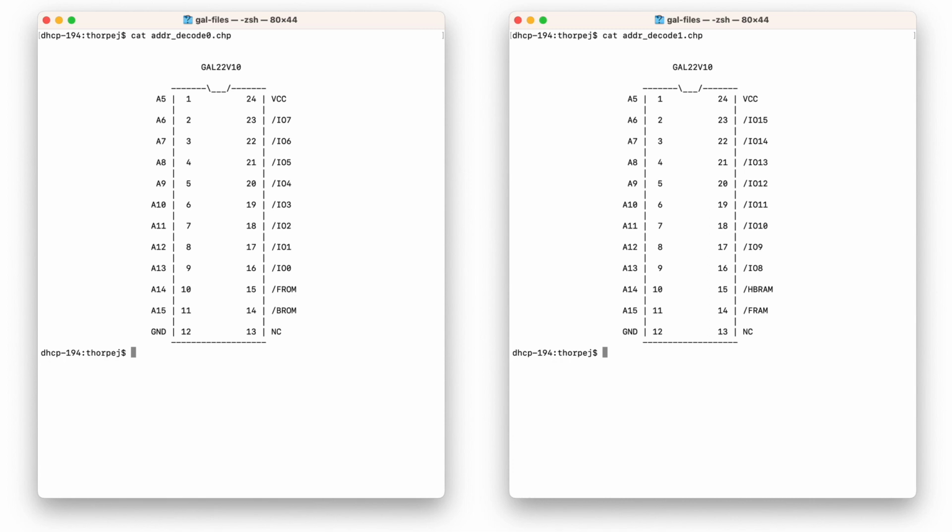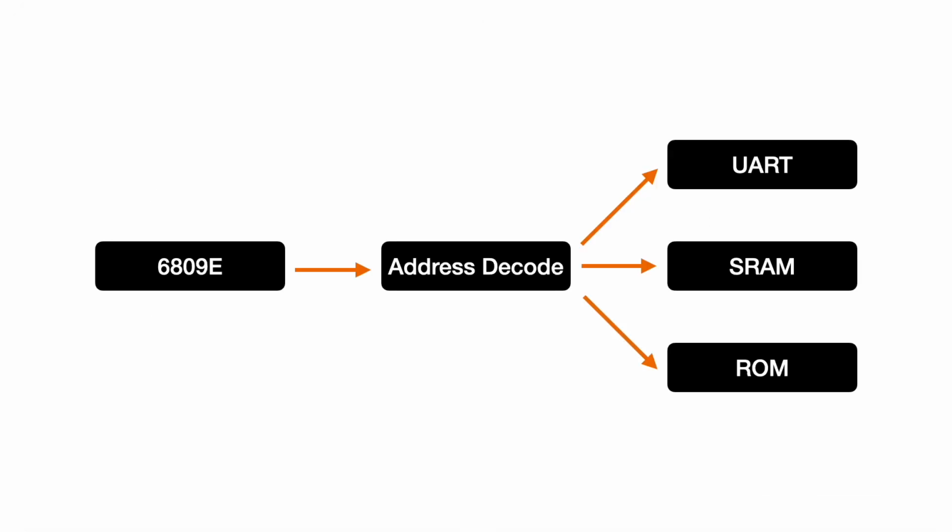So there you are with a complete address decoding solution and just 2 24-pin chips, with a low and uniform propagation delay no matter what address is being decoded. Okay, so we have another building block, but we're not quite done yet. We can decode addresses and select devices, but there's still the task of actually reading the data from or writing the data to the selected device. So let's take a look at what's necessary to do that.